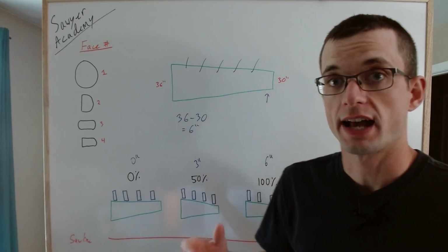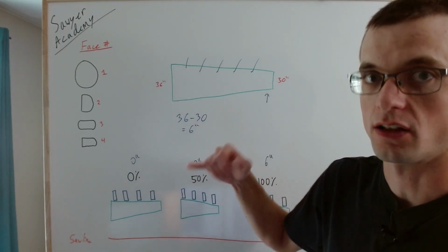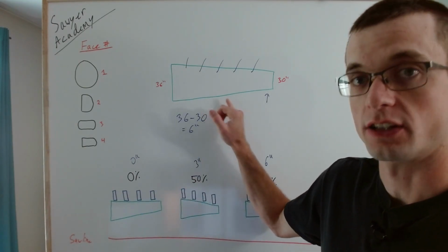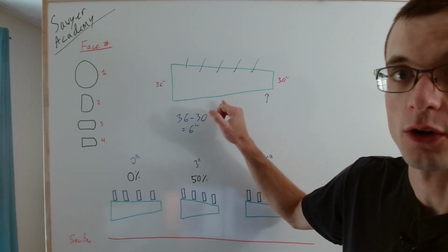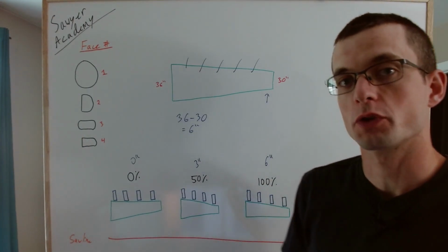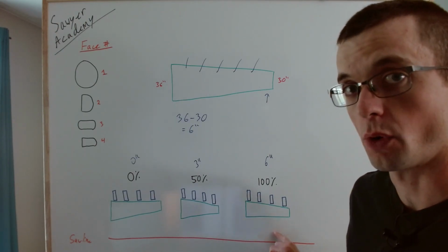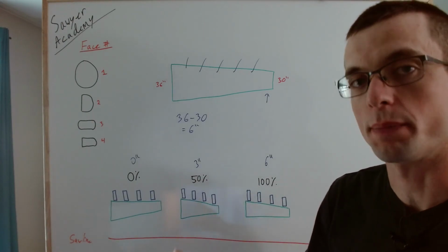If this is going to be our good face, as long as it's not too crazy, we're going to orientate that to our face 1, the nicest face to start with, and we could apply a 100% taper. Because what does 100% taper get us? That gives us very good recovery, full length boards off of face 1, and poor recovery off the opposite face.